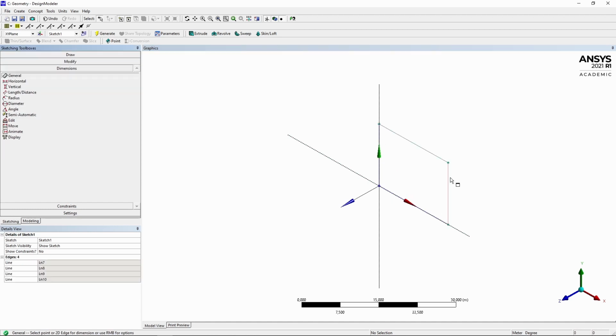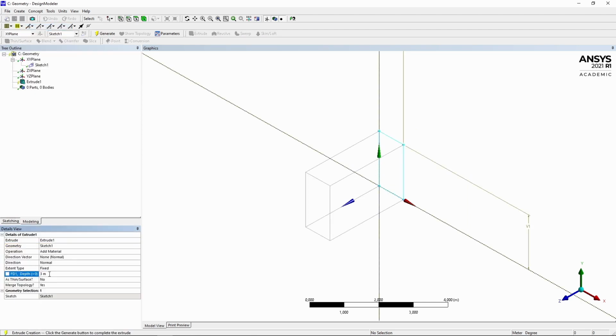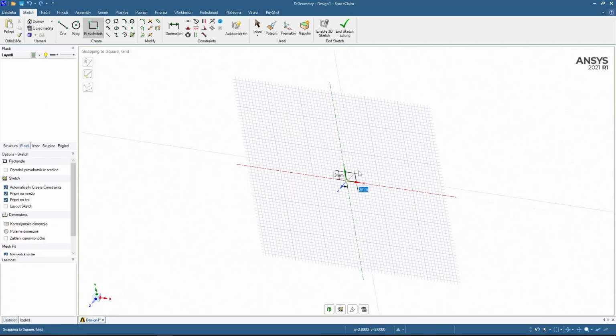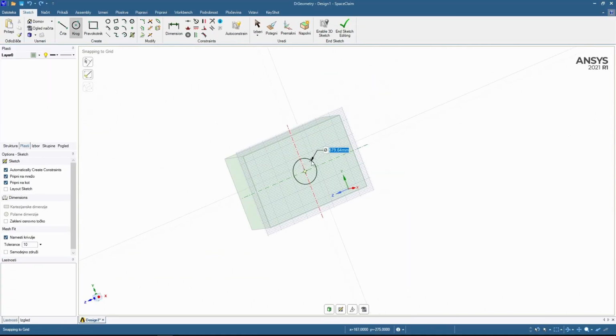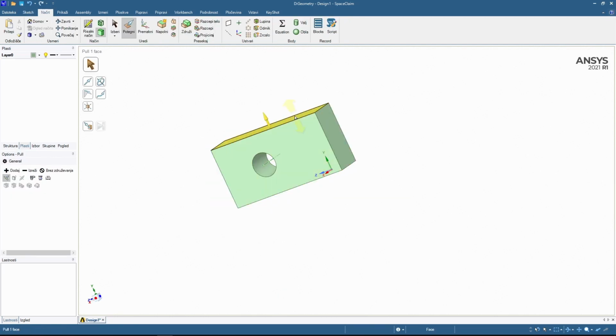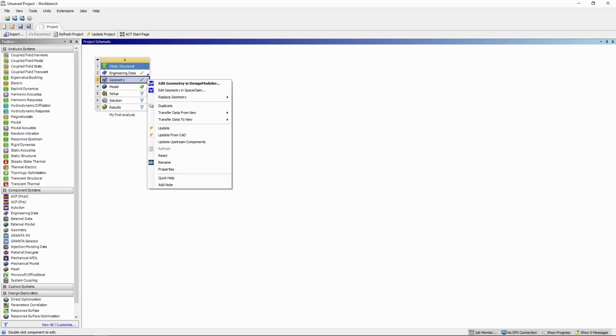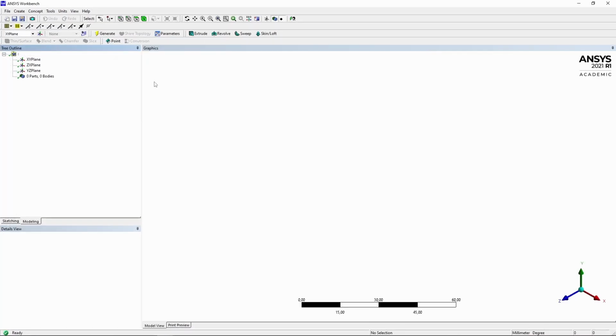options. Okay, so there are two applications for modeling in Ansys. DesignModeler is long established, conventional and original Ansys modeler. It might be cumbersome and have old-looking graphical interface, but it has good tree structure. I guess Ansys wanted to improve this somewhat inconvenient tool for something new, something better, so they introduced SpaceClaim Direct Modeler. Though it looks much better and supposedly it has some smart features, it hasn't convinced me yet, so I use DesignModeler. To open it, right-click on Geometry cell and choose Edit Geometry in DesignModeler.